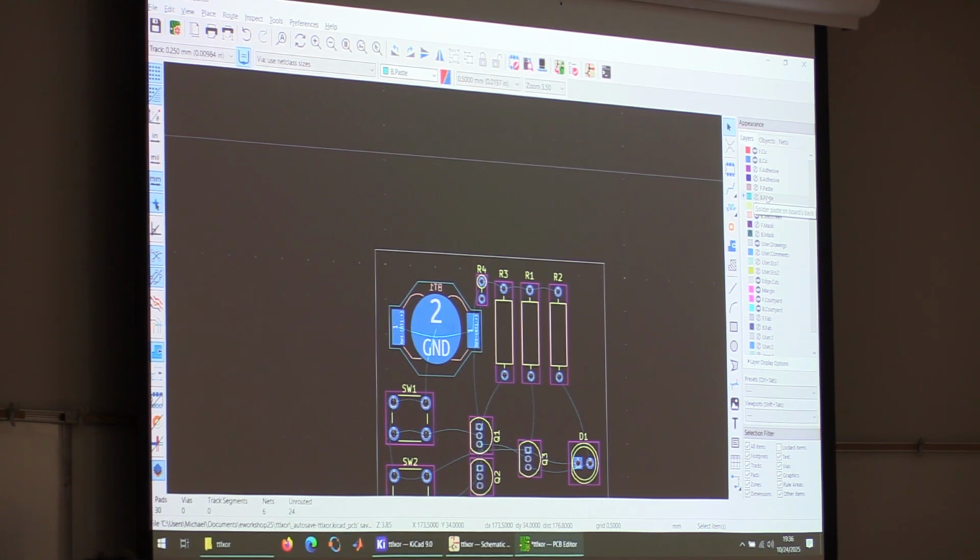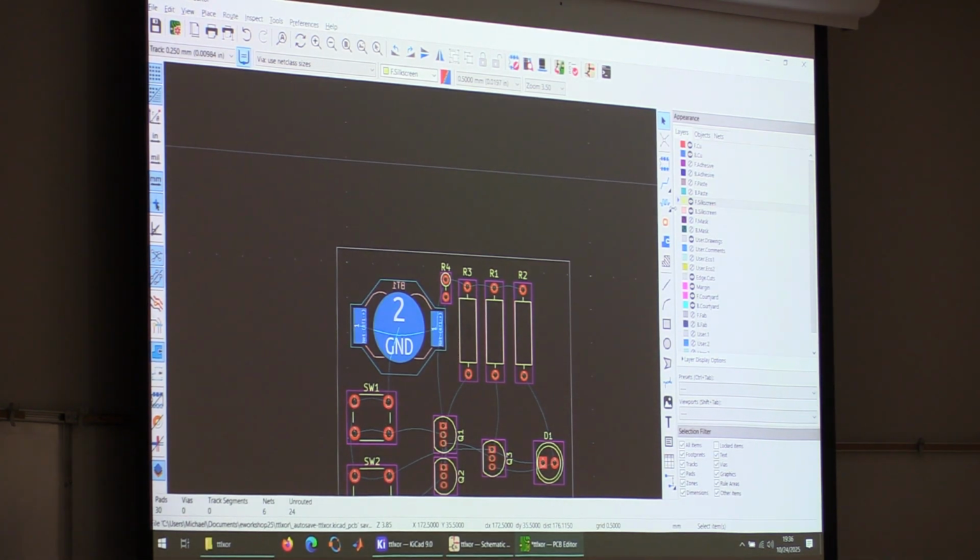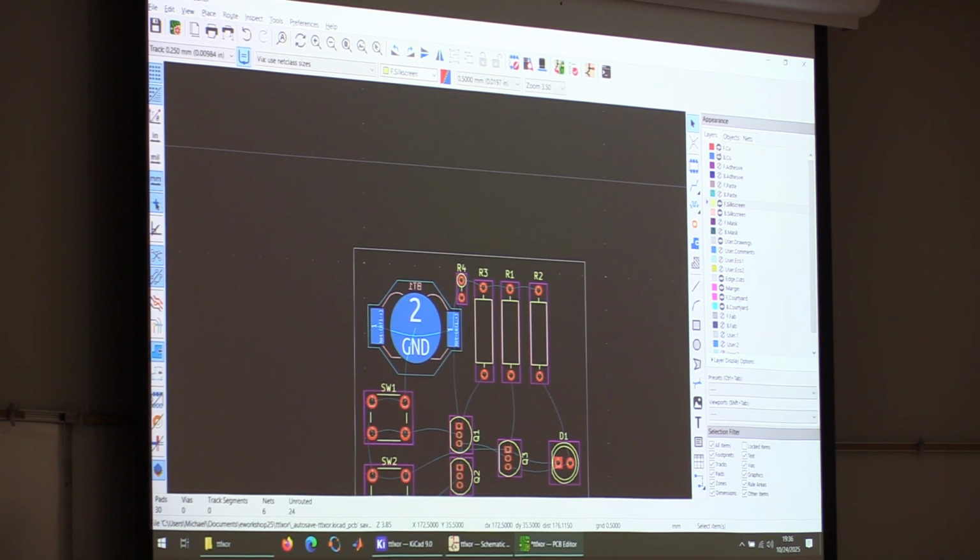Did you figure it out? Which one? The ones I would have selected are, if it is hard to see, I'm sorry. Make this bigger maybe? That doesn't help. All right. I have front copper, back copper, front copper. The first two here are shown. And I've got silk screen is shown. So if I hide that, then I'll only see the red. But if I show this, I'll get that. Same with the back silk screen. So maybe these are what you need to show. Did that work?